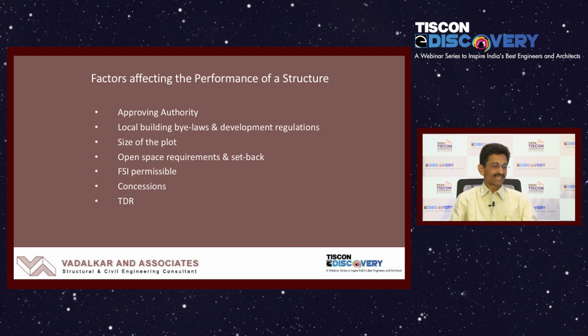Now when I say there are some more other factors, like the approving authority, that is also very important, because let me tell you, in the Gujarat earthquake what we observed was that there was some bylaw which was permitting construction beyond the building line as free of FSI, like balconies or projections that were not counted in FSI. So there was a natural tendency to build more balconies or bigger projections, up to 3-meter projections for balconies only. And afterwards people converted that balcony into a room, or some people even converted that balcony into toilets, which is not really desirable.